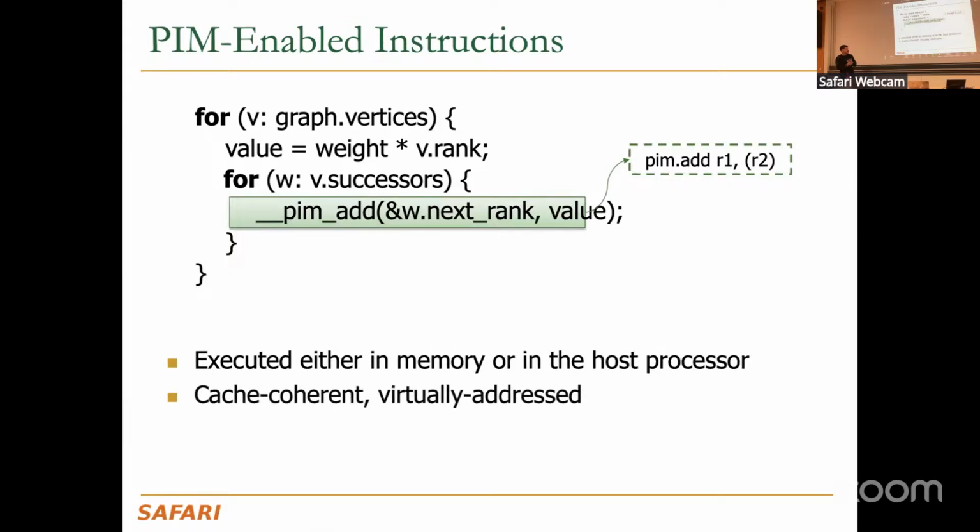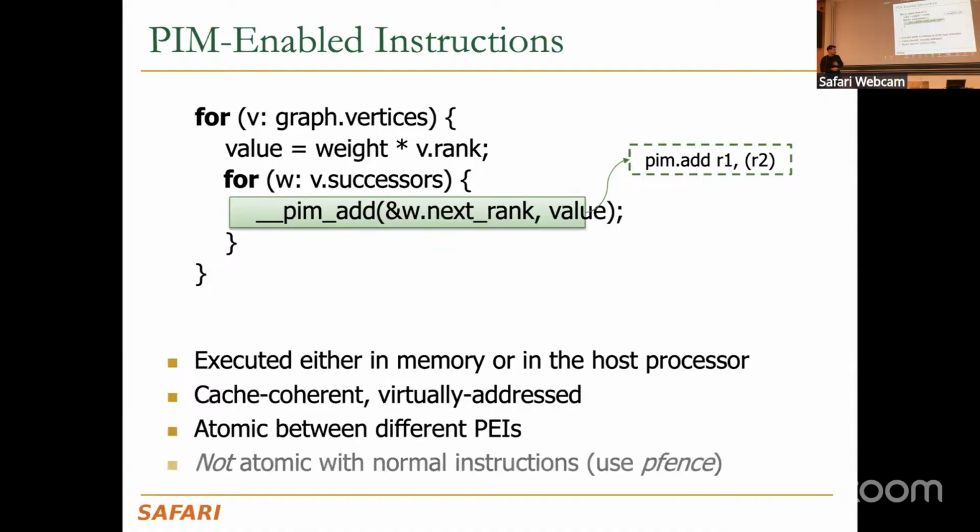By doing this, we can simplify a lot of system design constraints. Since we are only updating a single scalar value, we don't have to bookkeep a lot of data, and we don't need to worry about coherence for big regions of data, or generating virtual addresses, or mapping virtual to physical addresses for that particular range, because again, it's just one simple instruction that does a scalar update.